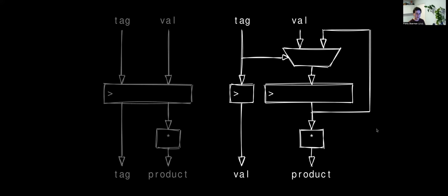But yeah, I think there's lots of fun stuff to explore with optimizations with higher level HDLs that you can't really do with Verilog. Definitely. And you can imagine, you mentioned the synthesis tools, how they process this more efficiently. You can imagine for different targets that might be done differently, right? For example, on FPGA, you may already have an enable on registers anyways, right?